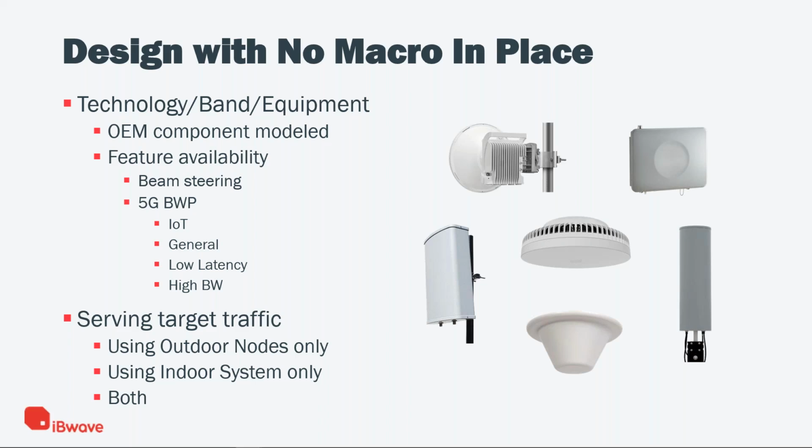You need to understand the impact not only of the signal into the building, but how much coverage you'll have and the quality that will be in the building, and what kind of devices will be on that network. And of course, the weak link is always the uplink. So definitely being able to understand the impact of that is going to be critical to your CBRS deployment or private LTE deployment.